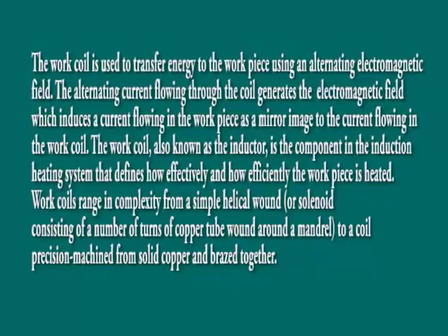Seeing the working of the induction coil. The induction coil is used to transfer energy to the workpiece using an alternating electromagnetic field. The alternating current flowing through the coil generates the electromagnetic field, which induces a current flowing in the workpiece as a mirror image to the current flowing in the work coil.